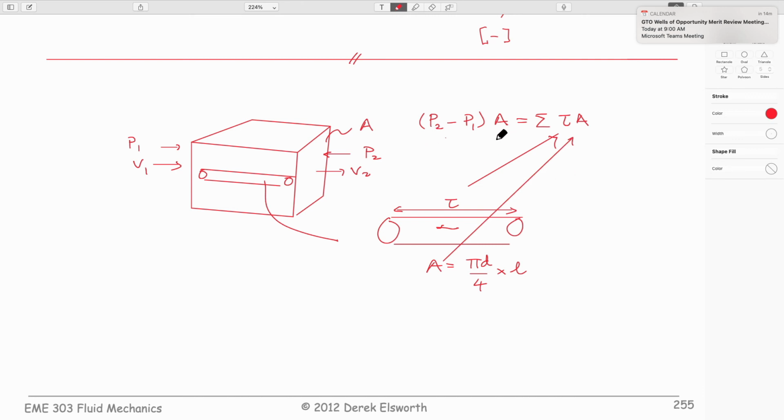So we'd use mass balance to say mass in equals mass out, and the difference between those is accumulation. And then we'd have to constrain it to account for the fact that we have viscosity here that affects this in some way. So we need some way of calculating the shear stress, and if we do that, we could calculate some function that retards the flow across it. And you might have seen it in your other courses. We call it permeability. And that is that the average flow velocity across the system is equal to a pressure gradient.